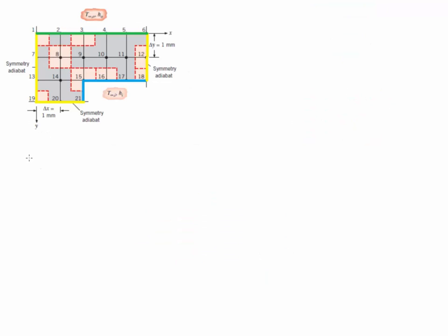The next step is to determine which nodes have the same boundary condition and determine the finite difference equation for each one of them. These nodes are located in a corner. They are exposed to insulation, conduction, and convection. The convection is to the hot gases. If we do a balance equation in each of the nodes, we will be able to get the following finite difference equation.